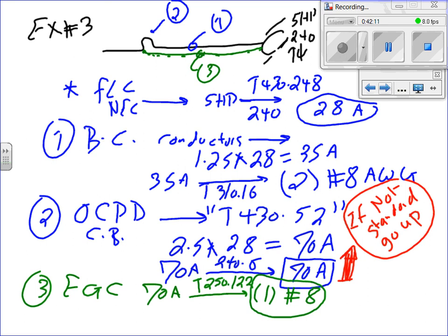Because we oversize the overcurrent device for motors, under certain circumstances this conductor might be number 1-aught. It could be that the grounding conductor is 1-aught and the phase conductors are number 8. It will be, if you use certain circuit breakers. What would you do in a situation like this? Here's what the code tells you to do.